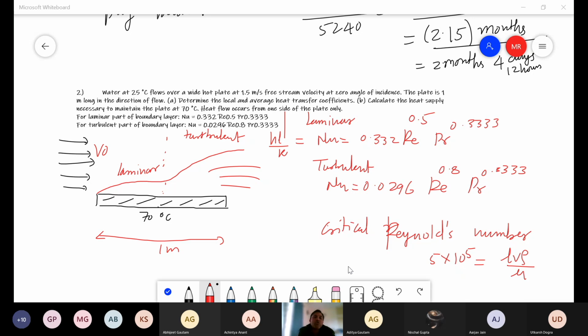That is because we don't want to calculate the effect of thermal conductivity, viscosity, and velocity change in the system when there is a flow of fluid. Instead, we calculate the heat transfer coefficient based on data, using some empirical correlation, and directly use it in Newton's law of cooling to calculate the heat transfer, instead of solving the entire system from first principles. That's what we said when we started looking at the concept of the heat transfer coefficient. Do you all agree?